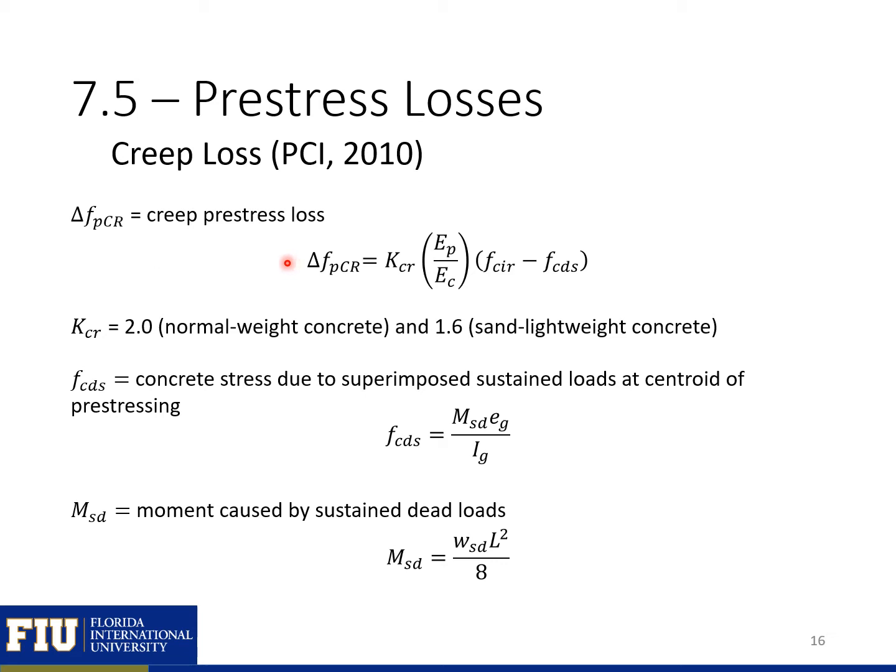You can see here the creep loss is a factor of the stress that we calculated from elastic shortening and any stresses that are caused by the superimposed sustained loads at the centroid of the pre-stressing strand. So we can calculate this value used here.